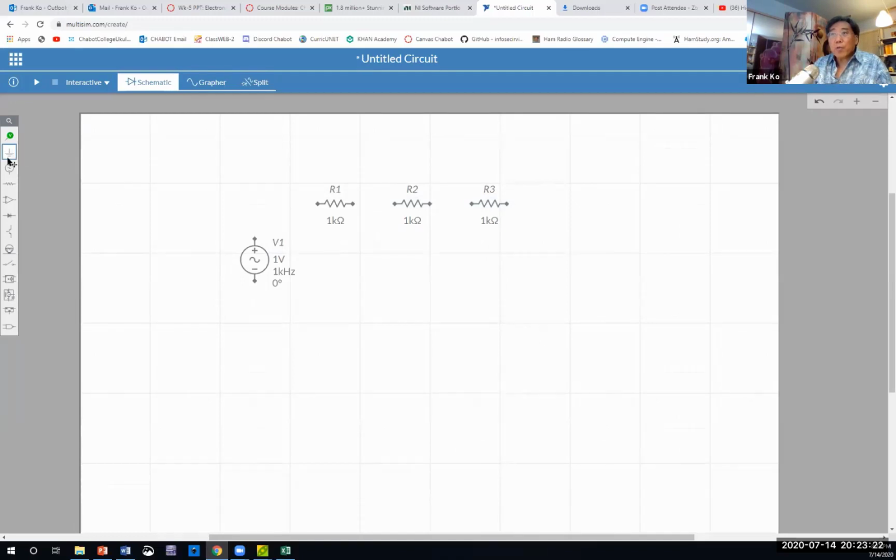And I'm going to come over here, schematic connectors, bring a ground, and I'm going to bring the ground over to here, let's say. So now do I have components placed on my board in a fashion that is similar to Tina? So far, it's very, very similar to Tina. Okay, just give these some spacing apart.